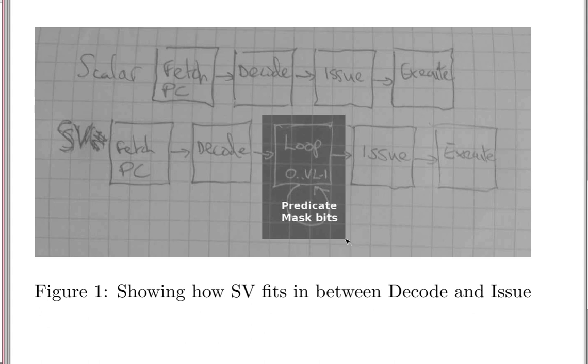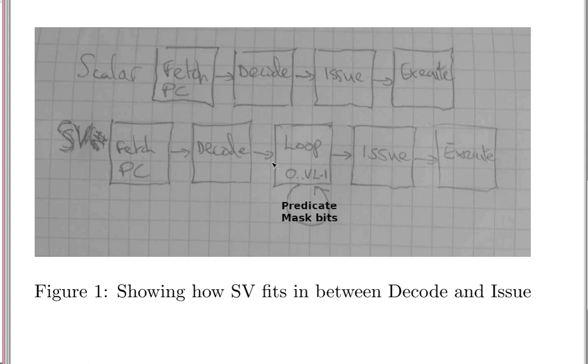It should be fairly self-evident how that would be multi-issue executable, and how predication can be inserted on top of an existing scalar ISA, which does not itself have predication, as it simply tells whether to skip that unit or not. And then on top of that, we've worked out that you can do hardware looping. This loop 0 to VL minus 1.